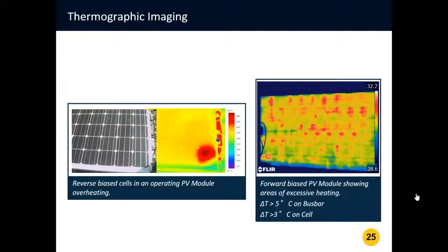If there's a failure in the electrical connections, or something like the thermal image, where there's obviously a significant hotspot present, that could result in a fire in the right conditions. So erring on the side of safety would be to replace and remove a module at a certain hotspot level.